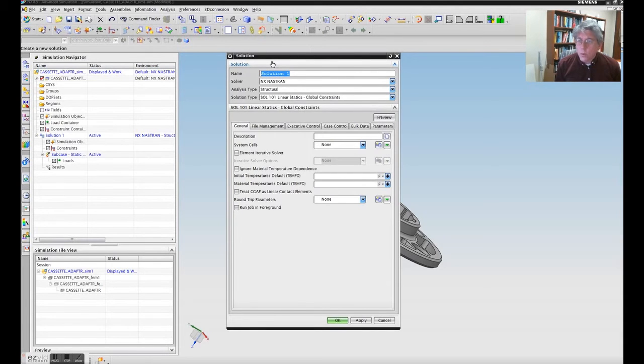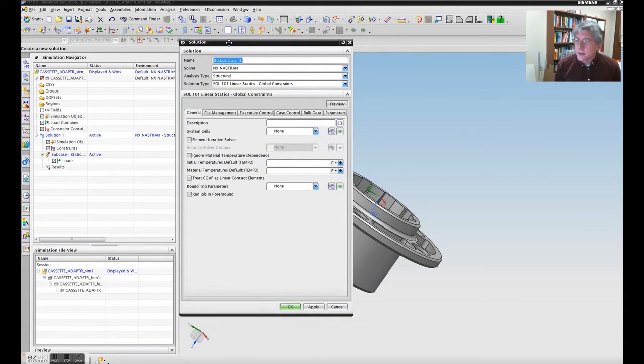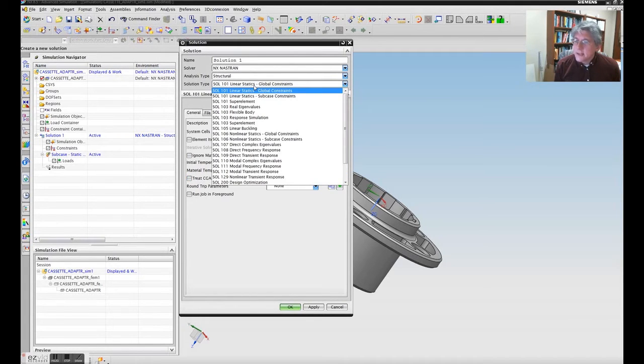Okay, so it's going to use linear elastic static solver 101 in Nastran. Keep everything the way it is. Honestly, you can run different types of analyses in here. Typically I've done modals through here, but anything more sophisticated than that, I usually find it's easier just to go through another preprocessor. Okay, so we'll keep it at solver 101.